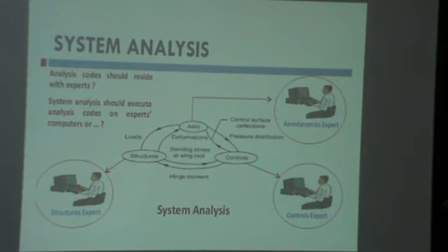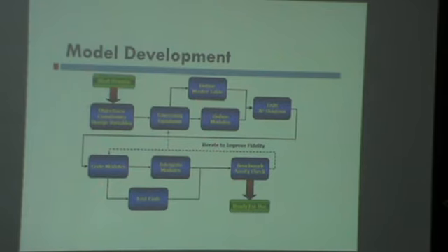Okay, so this is where it is. Over here, the aero people, the structures people, and the controls people have all come together to define a common objective function. So now, instead of the objective function being different for different points of view, you have a common objective function, and that is to check the deformations or the bending stresses at the wing root. There were many subsystems, they did their own analyses, but now they have gained a common objective function. So this is how you develop a model.